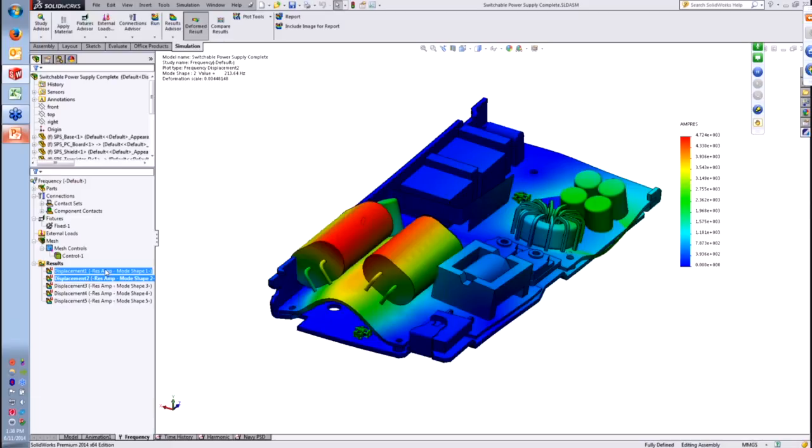However, this information is going to be used via what we call modal analysis to predict in those more advanced study types what the real stresses and displacements actually will be once we define a specific input load. So the frequency analysis gives us an idea of what directions the product might vibrate in and what frequencies it might get excited at. And the linear dynamic studies will tell us the actual results, the displacements and the stresses.